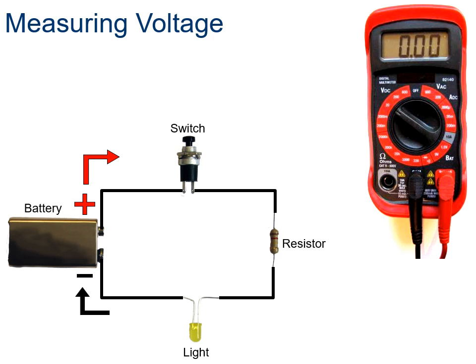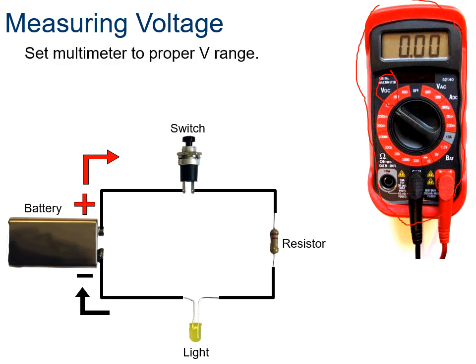When we're measuring voltage, we use this device over here, called a multimeter, and we're using it on volts. You'll see right here, this switch is pointed toward V, which is voltage. We set it to voltage. For a 9-volt battery, typically we want to set it to 20 volts. Most meters have a 20 volts setting, and we want to use DC. DC is the kind of electricity that's stored in this kind of battery. AC, which is this one here, is what comes out of the wall.